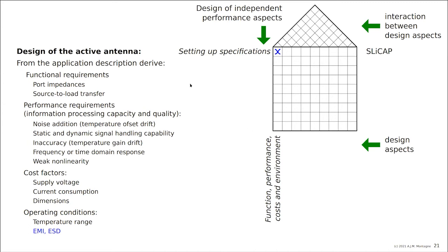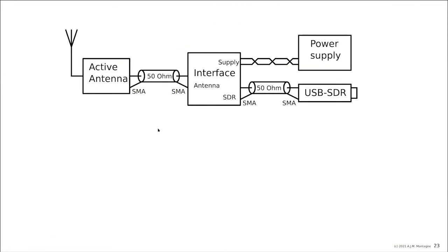So let's have a look at the antenna specification and see what we can find from there, if we can make it complete. That's what we did basically. So the next is here. Maybe you remember this picture. This was our assignment. We needed to make the active antenna. The antenna itself was a capacitive rod, and the active antenna should drive a long 50 ohm cable, and the rest on the right is just for the contacts, but we didn't pay any attention to it during the design.